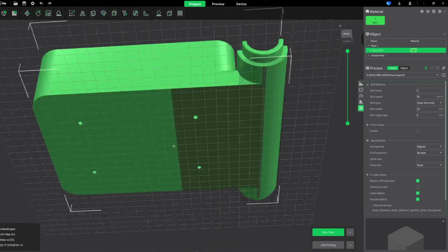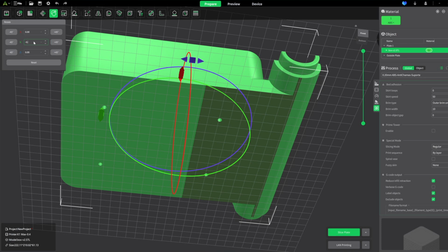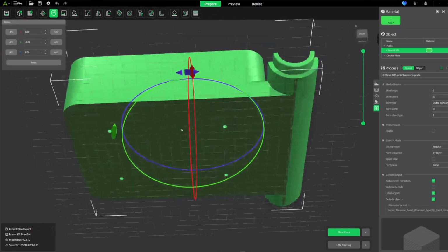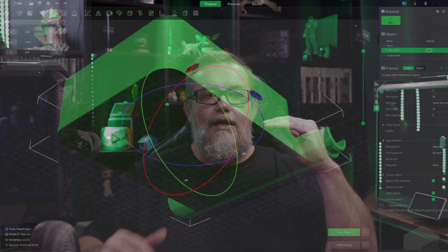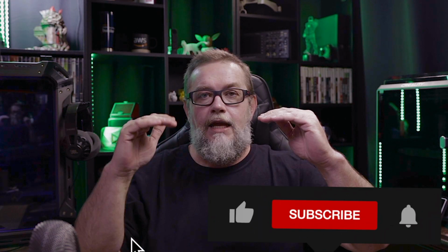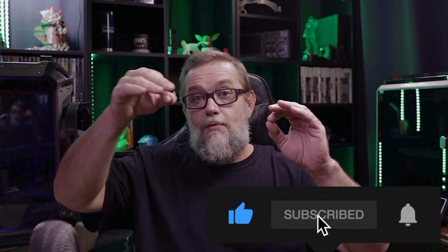0.04 degrees to make the object perfectly aligned to the bed, even doing that, when I try to print that part, the printer tries to print the first layer on a different level of the bed, like it prints on the air. It's so high compared to the bed that the printer literally starts printing on the air, and on the other side of that part, the nozzle almost scratched the bed. So it's not just about the object leveling on the bed, but it's about how the slicer is generating the G code and sending that G code to the printer. So it's a very grave bug.